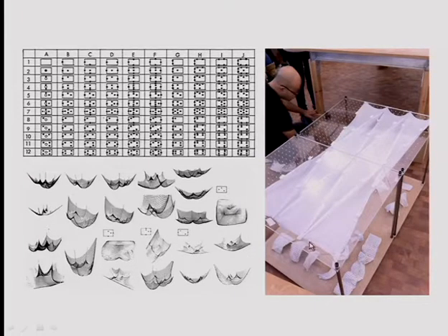So what you see is that you generally take a sheet of perspex so that you can puncture it with a grid. You make a set of holes and you generate a grid, so that you see this table here. You define where the suspension points, so the support points, are, and you play with them so that you can define a family of shapes, a family of possible solutions.